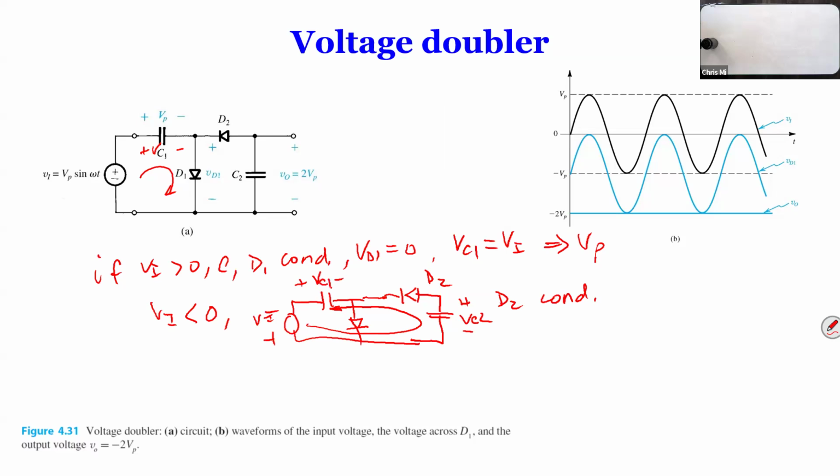Because the middle diode does not connect anyways, I'm going to just remove that, to make it easier. I mean the middle one, the middle D1. The D1 is reverse biased, no current, so I just take it out. It's just easier for you to look at the loop. You don't have to take it out, but it's easier to analyze. So now look at this circuit. This is one loop. And again, assume VD2 is 0, ideal diode.